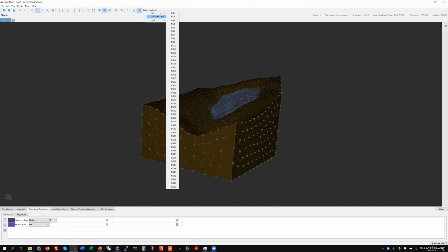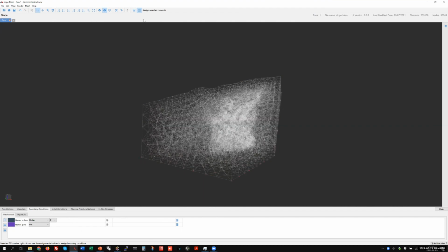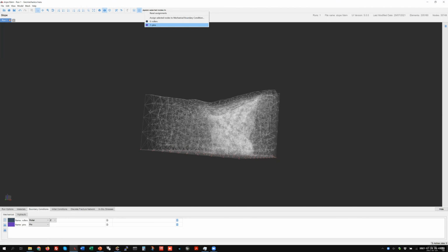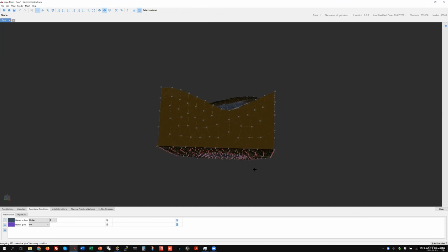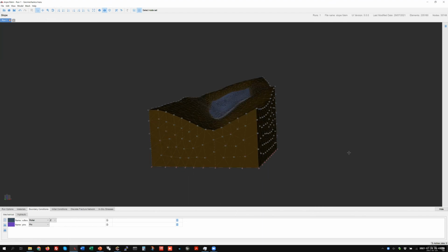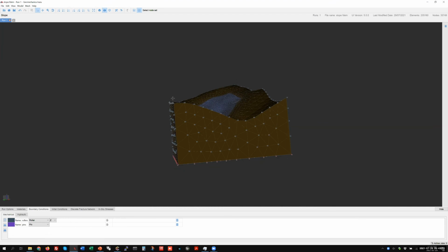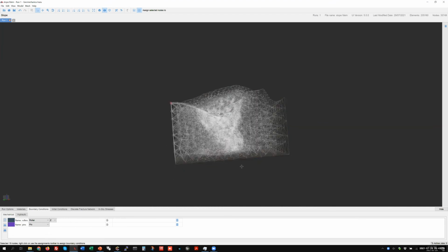And as you notice, if the names of your node or element blocks are similar, then Irazu will try to group them for easier processing. So node set 3 are all the nodes at the bottom, and you go ahead and assign pins to them, right? Very easy. It's so much easier than having to manually select things. If you want to graphically select all the nodes on the side, then you first of all have to be very patient and then ready to make mistakes, right?